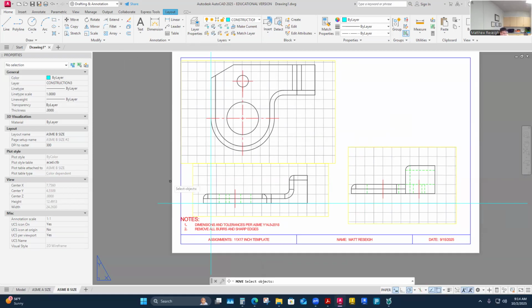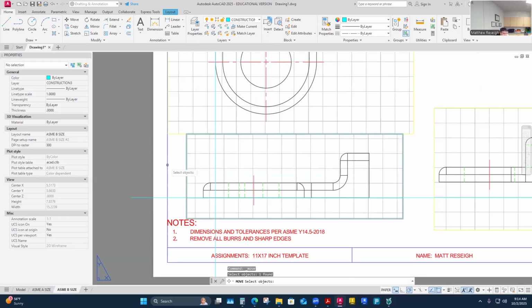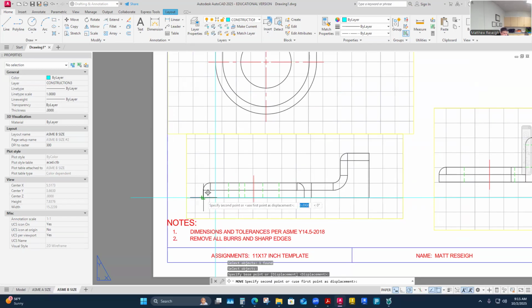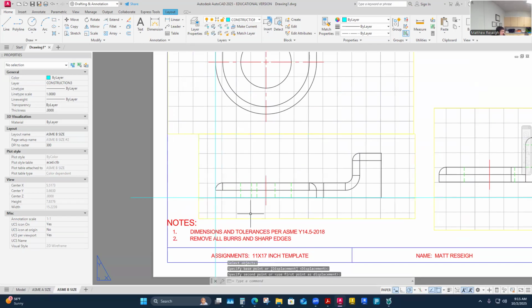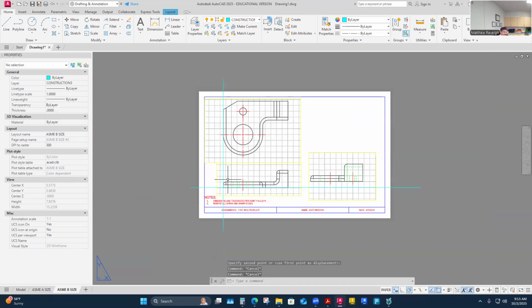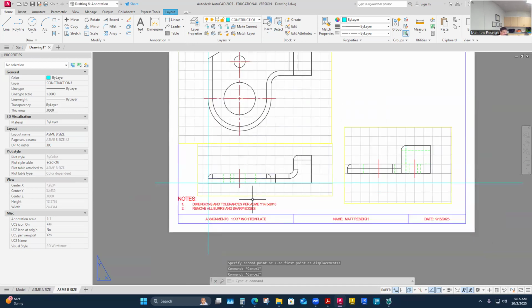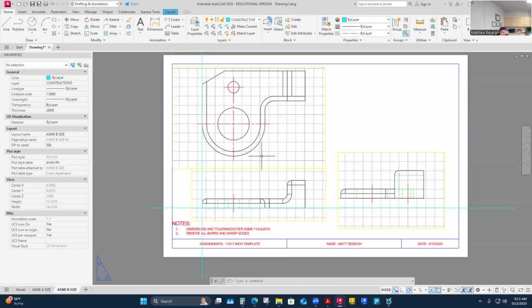So then I just use the move command, and I'm gonna move it from the viewport. I'm only selecting the viewport that I'm moving, and then I get all the grips within the viewport, even though I'm not technically clicked into the model space, and I can use the grips, which is kind of handy. So that's an orthographic alignment top to front with maybe enough room to dimension.